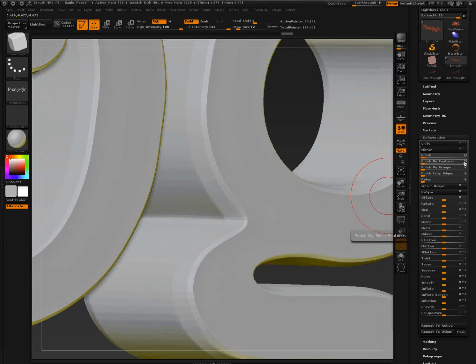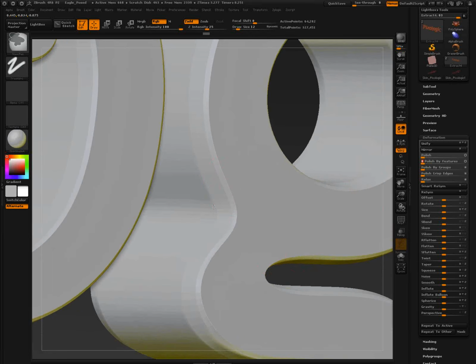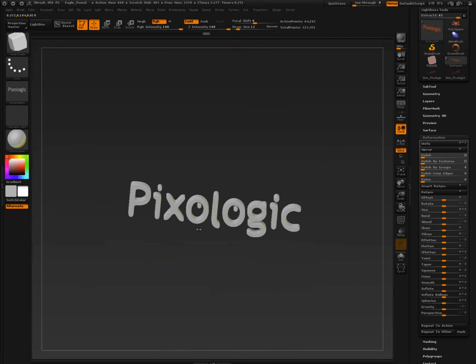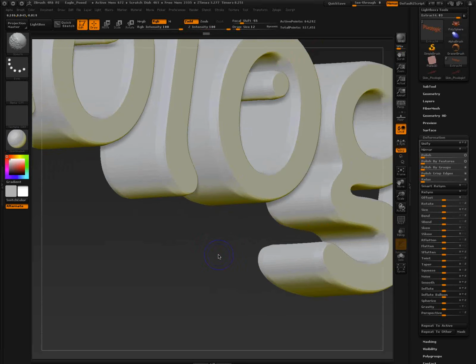In fact, I'm going to open the circle because there's 2 algorithms here. There's a closed circle and there's an open circle. Okay? So with the open circle, it's going to allow shrinkage, but it's a lot stronger. So watch what happens. So you can see how much stronger. See the nice panels I'm getting here? But it's also shrinking, but you can see how clean that is now. Nice and clean. And I'm only sitting at 64,000 polygons.